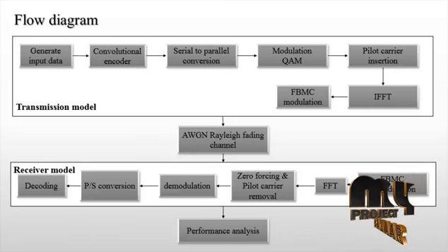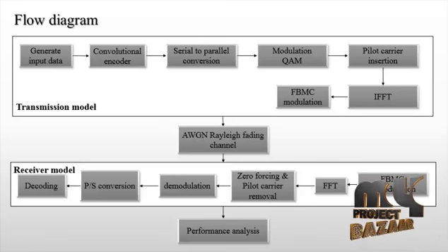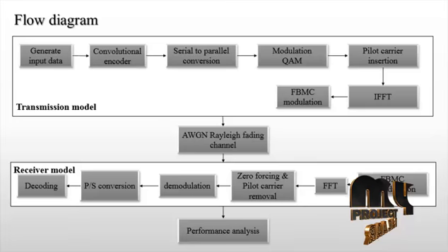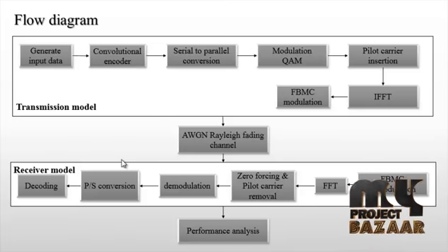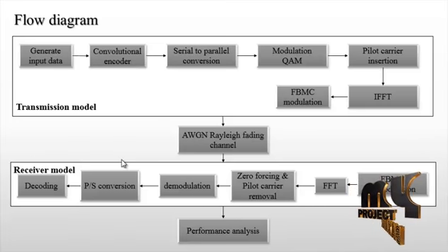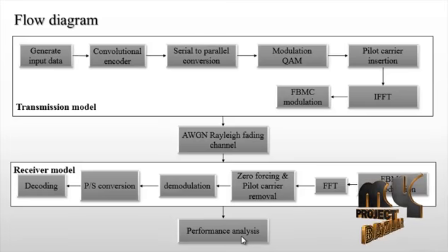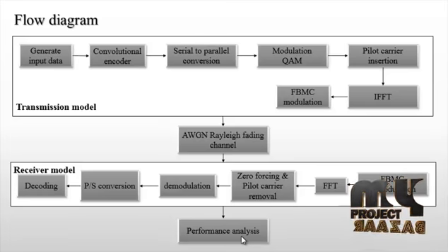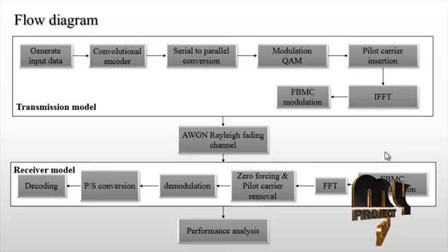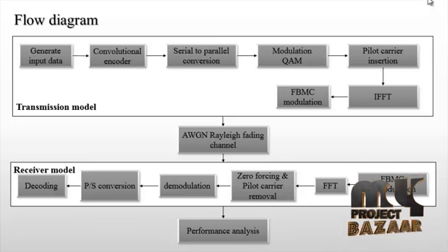Finally, we calculate the performance analysis. The output of analysis is referred to as a subband signal, and the filter bank reconstruction process is called synthesis, meaning reconstitution of the complete signal resulting from the filtering process. We calculate the performance analysis using the bit error performance and the symbol error rate. So this is the overall flow diagram of the process.